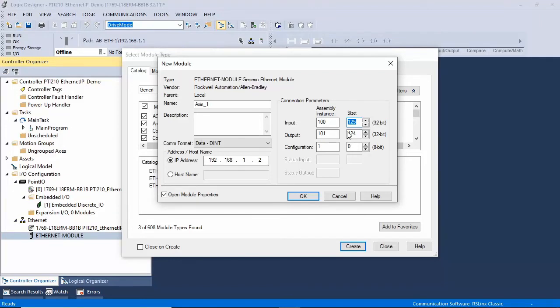So as you recall, the input to the PLC would be the master receive. So that's only going to be 2 words. We're only sending position and then the bit mapped drive status and drive enable. Now the output assembly, that is going to be the master send in the PowerTools Studio side, and there were 3 data words for that. So that's all we need to do. Let's click OK.